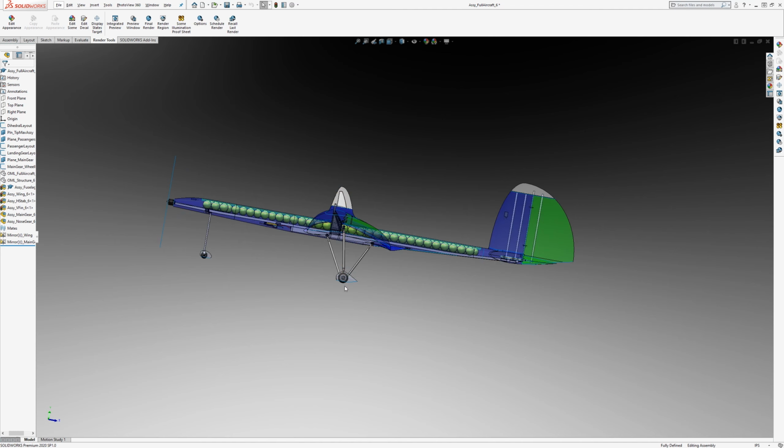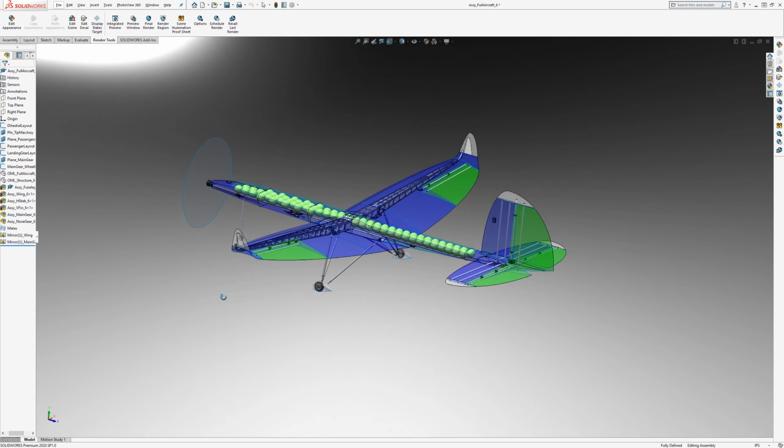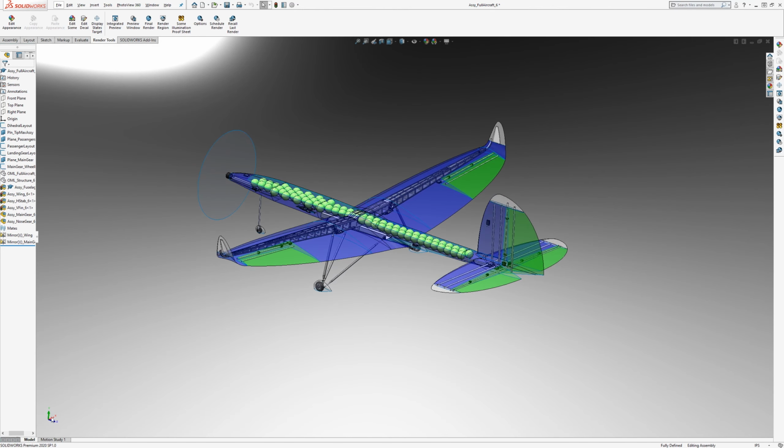So when we hit the ground, there is a torque, sort of a pitching moment forwards. So there's going to be an angular acceleration on the aircraft. So in addition to knowing the masses, we need to know the mass moment of inertia about the, well, in SolidWorks it's the x-axis here.